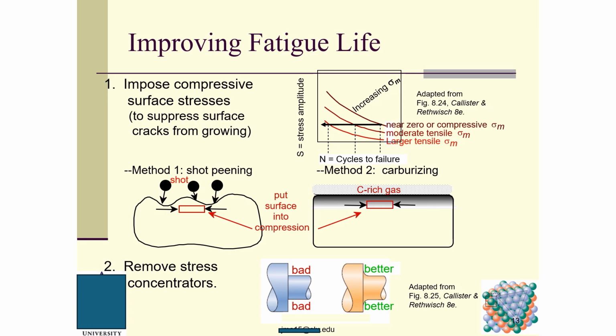Residual stress means that even though these particles finish impacting the surface, the stress is still there, residual stress. You should know that compressive residual stress improves fatigue life.